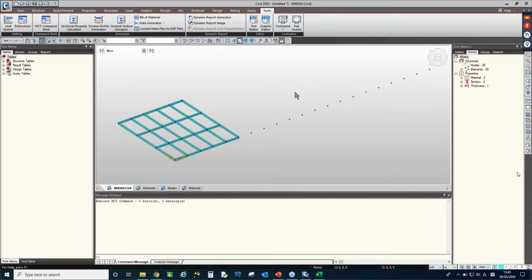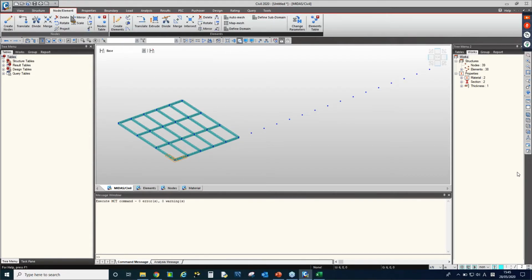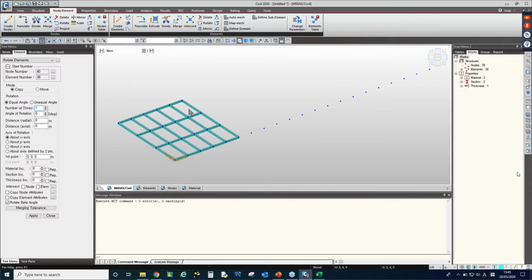So if the cross beam has radius, we can rotate, I guess, the element. So you can select the first cross beam and then input the radius of the curved bridge, and then set up original point. Then I think you can make the cross beams for the curved composite girder bridge.